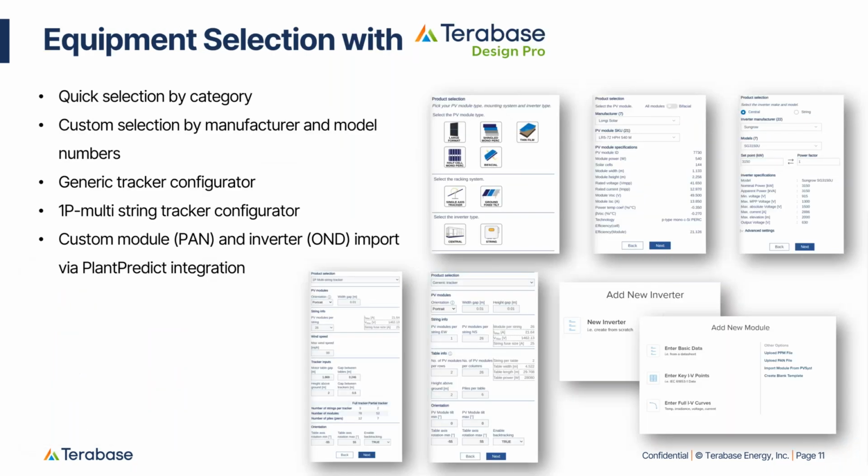From there, you'll specify the solar panels, the racking configuration, and the inverter that you want to design with. We have quick selection tiles to simplify this process, or you can customize your selections if you want to dig into the details. Using the module and inverter library from PlantPredict, you have access to thousands of global files, or you can upload your own PAN or OND files to build out a module and inverter library that is controlled and accessible only within your organization.